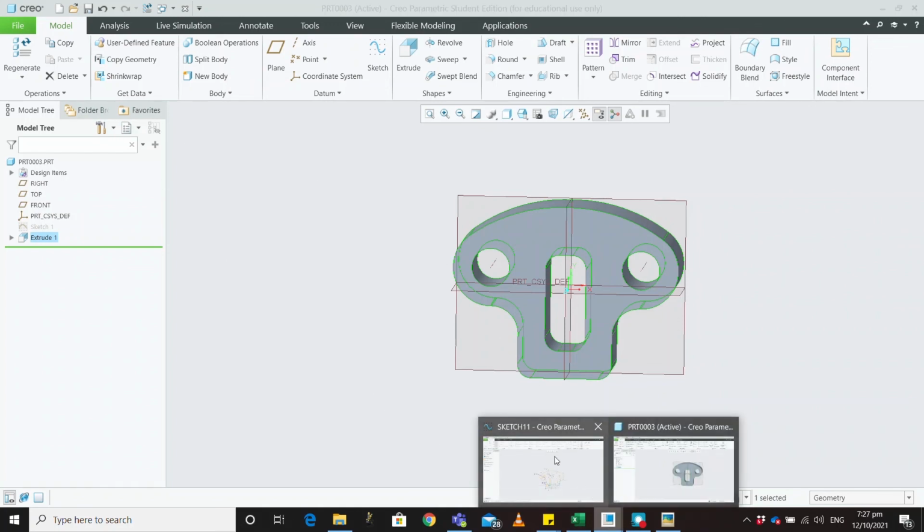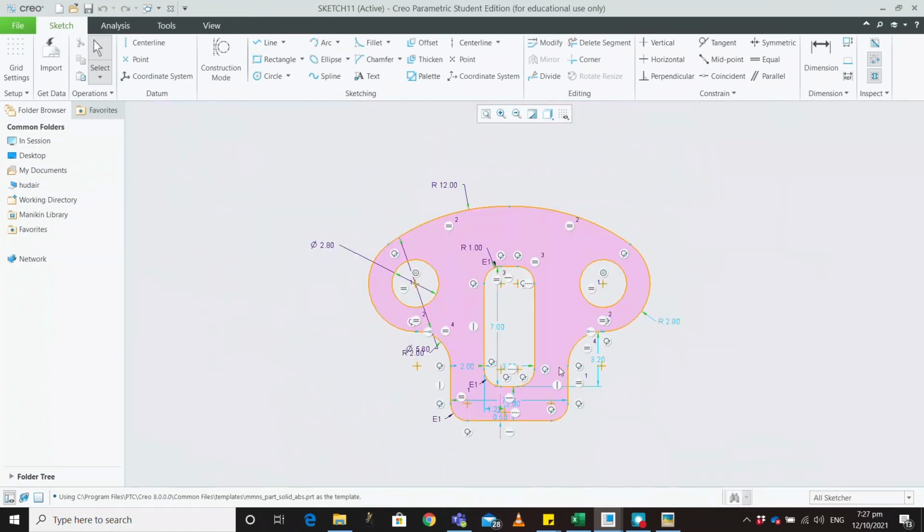For this session, by the next session, you should know how to set the working directories, how to make sketches, how to use the delete segment command, the line commands, how to exit the commands, how to use mirrors. We can mirror the whole parts too in the same way. Just try to have fun with these basic things: line, rectangle, spline, arc, fillets. Try to find some online CAD drawings and try to remake them over here in the sketch mode.